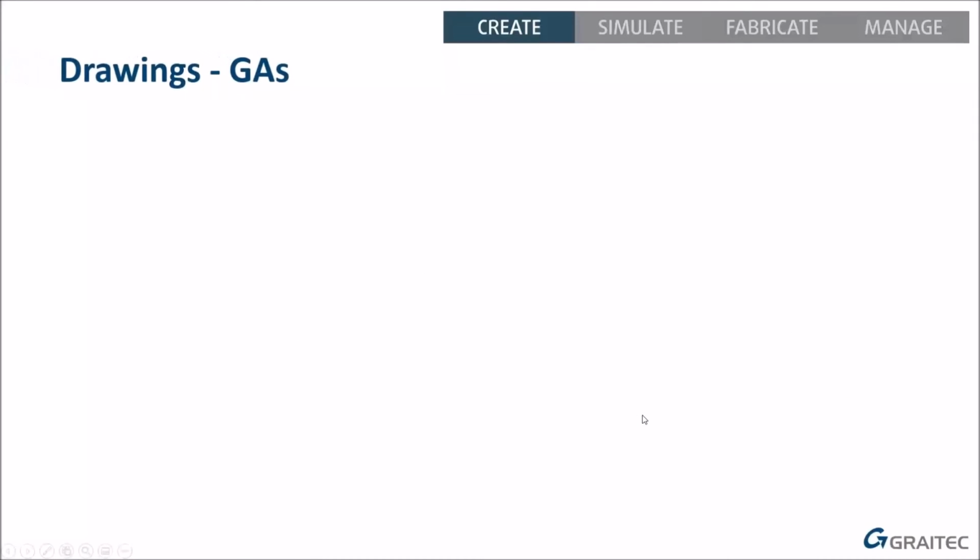So how about generating drawings? Once you've got your user section in there, you can just use that in the cladding macro as normal, like any other section. It will always place it in the standard presentation mode, so it'll always just come in with the flush flat front panel. You can change it to the exact presentation mode if you wish for your pretty pictures, but it won't show on the drawings. Let's have a look at the drawings.